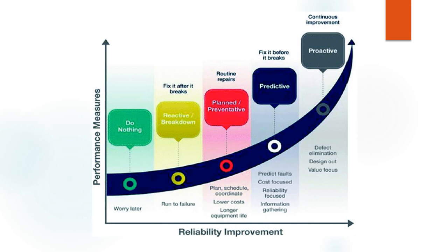This criticality can affect production, power generation, human life, the environment, and the reputation of the company. What do you think in this case? Is it critical or not? Which is the most critical? Then we have a criticality matrix. This matrix gives us a certain criticality according to all these parameters. And according to this criticality, you start to consider the type of maintenance or the effort you have to put into this equipment in order to keep it running in a reliable and available way.